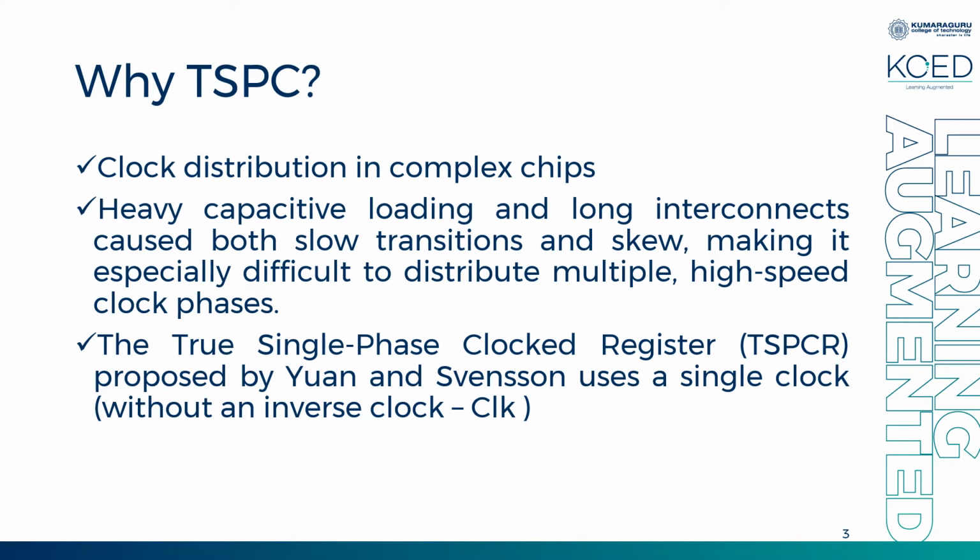Okay, and the main problem is clock skew. For example, in dynamic logic style we learned that when you cascade dynamic logic style, you face some problem. You saw there is some problem in the transition. Now if there are 4 stages, we have to give the clock to each and every stage. For all the stages, clock will not go at the same time. That is clock skew. And it will not be acting in the same way because clock is not distributed at the same time.